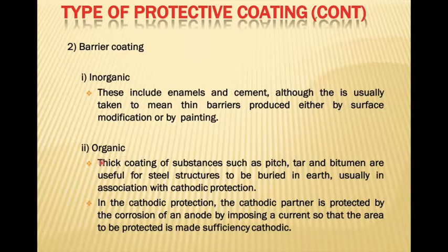Then organic thick coatings of substances such as pitch, tar, and bitumen are useful for steel structures to be buried in earth, usually in association with cathodic protection. In cathodic protection, the cathodic partner is protected by the corrosion of an anode, by imposing a current so that the area to be protected is made sufficiently cathodic. So we are going to use a current in order to protect the